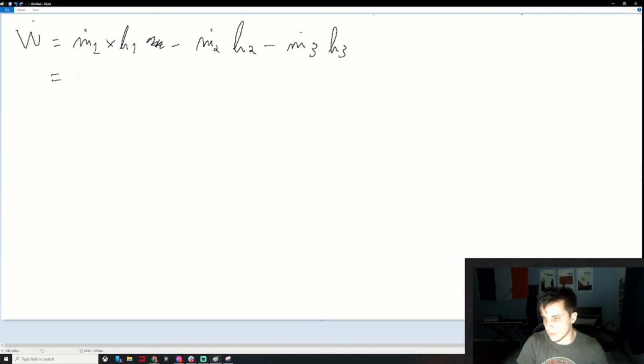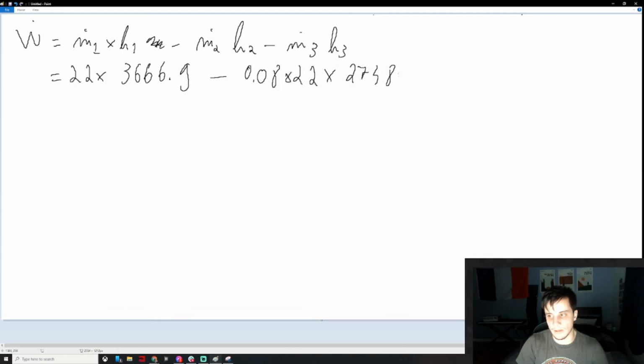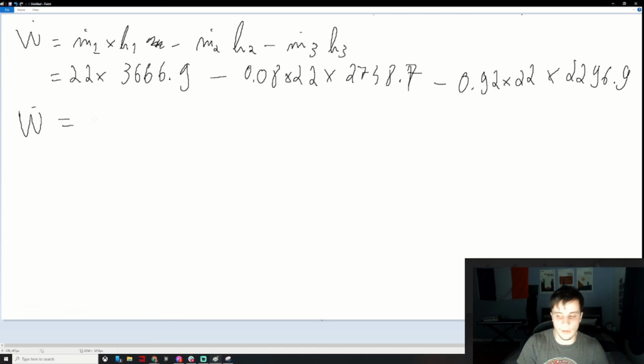Just plug in everything. It was 22 times h1, 3666.9, minus m dot 2, which is just 0.08 of 22, times 2748.7, sorry, and then minus 0.92 times 22 times, we found it to be 2296.9. Okay, solve everything, and you should get a work of 20,346 kilowatts.